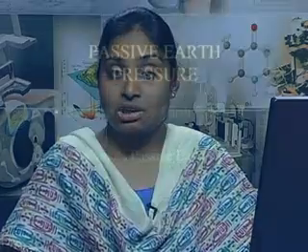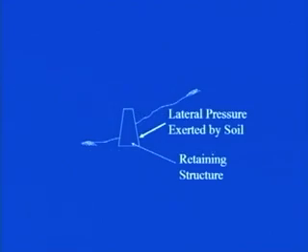Now, this was all about active earth pressure. Let us come to the third one, that is when the wall is moving towards the soil, and I explained earlier in the previous class that this particular condition corresponds to passive earth pressure. From common sense you can find out, this soil is exerting lateral earth pressure on the wall, so the wall always has a tendency to move away from the soil. In what case will it be moving towards the soil?